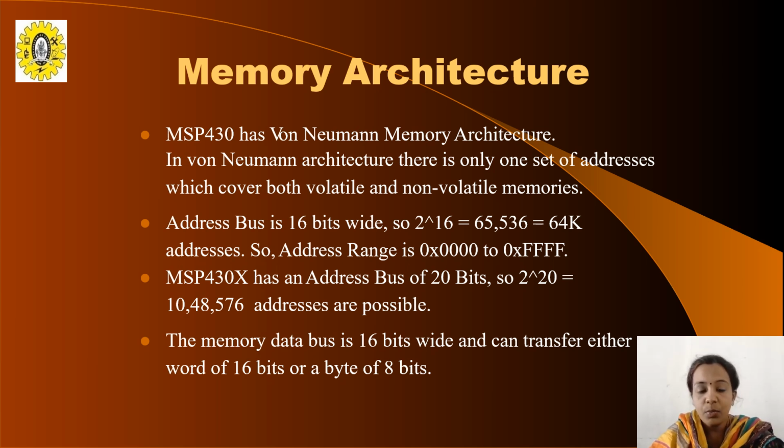So the address bus will be having 16 bits. 2 power 16 is nothing but 65,536 address lines that can be used. Addresses can be transferred. So the address range will be from 0x0000 to 0xFFFF.